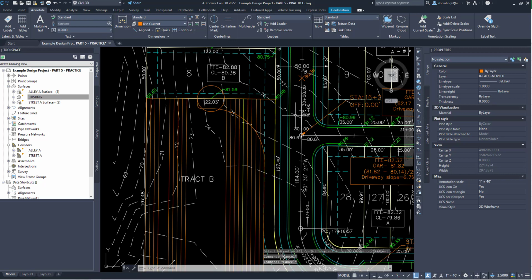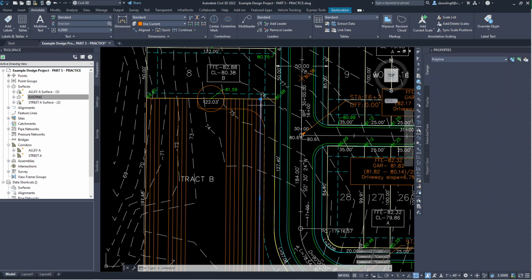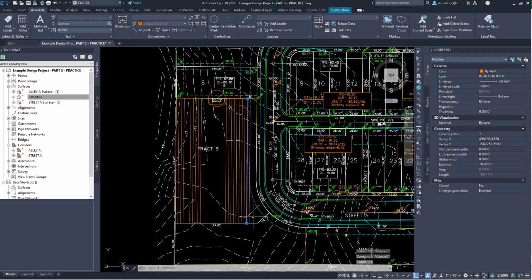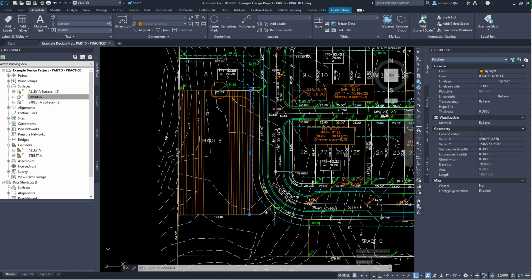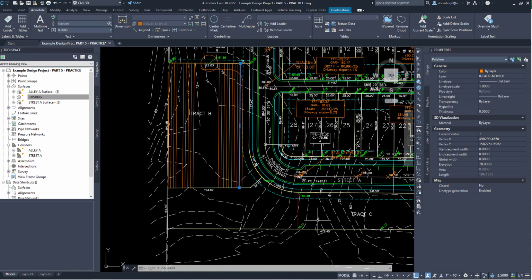All right. Now from here, I'm going to use 20. If I have to use retaining walls on the inside, I'll use retaining walls on the inside because that's just too big of a radius right now. We're losing a lot of land. So I'm using a radius of 20. Now, I shouldn't have bothered with the contours labeled here, but I'm not going to worry about it for right now. So the 69 contour is right here. See this elevation right here?